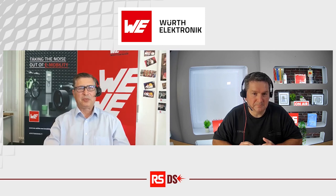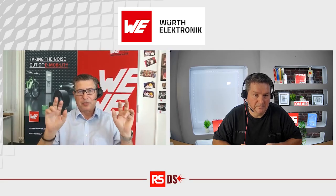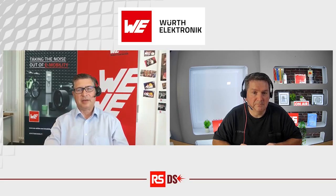Well, when I do a new design today, I always think already on the schematic about the EMI issue. I will put on at the beginning a 0 ohm resistor and keep a pad free for a capacitor for at least an LC filtering for my power supply or for my data line. Then the ESD issue is also very important. I will also put a pad, as small as possible, which just fits to the connector, in case I fail the ESD test, the final test after the EMI test.